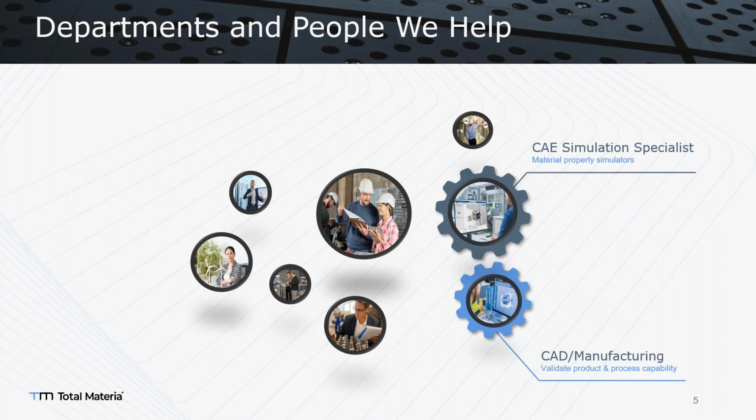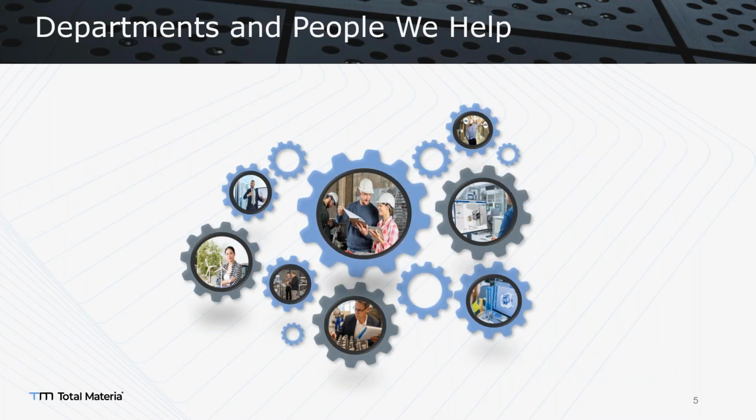Still, it's starting with the material engineer. If it's compliant, send them the material list. Let them make accurate simulation results. When you're making a design, you're just using the material cards. You can export from Total Materia, and your simulation result will be more accurate than before. All this communication within different engineering departments is very important for you to make an accurate and very efficient workflow, right?